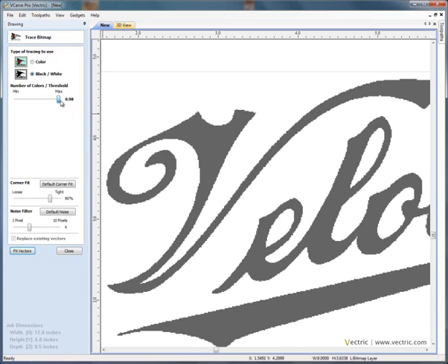So we have a slider here to control the level of detail that is displayed for the selected JPEG. So if we drag this up to, let's say, about just over 80% or 0.82, we can also control how tight the vectors flow around the selected image or how loose they are. So by selecting the slider here, we can have a very loose fit, or if we say very tight, then a vector will be fitted exactly to match virtually every pixel in the design. I tend to find that a tightness of about 80% normally gives very good results.